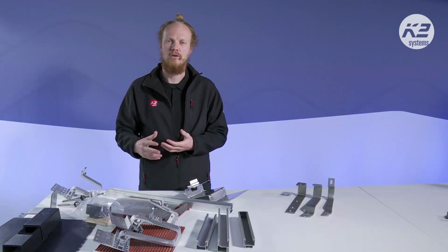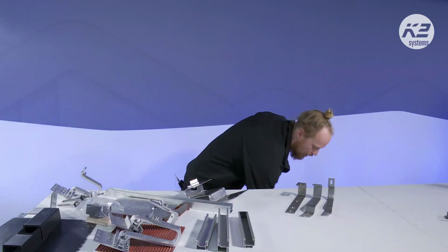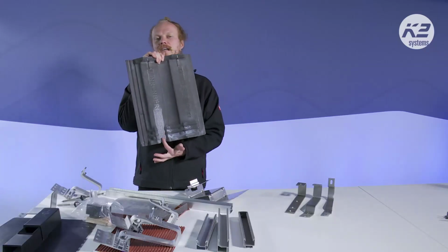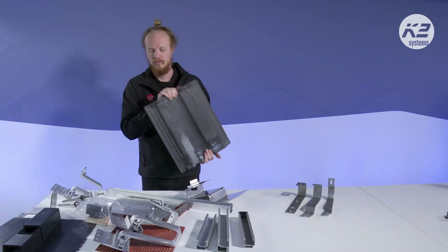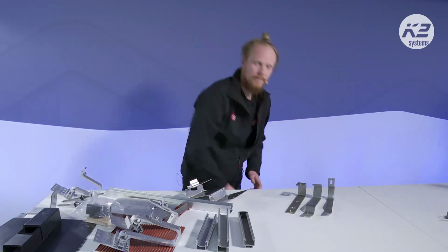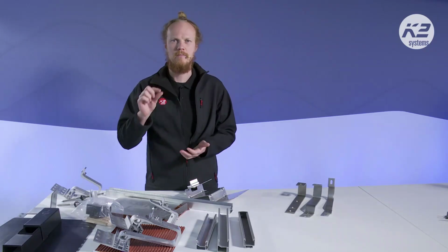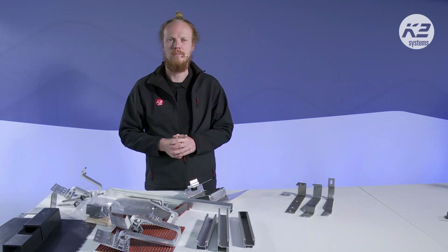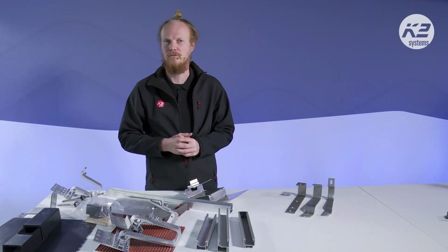Potentially the methodology where we grind the tile, and I just have a little sample here that we spoke about last week, where you can see part of the tile has been cut out. This is usually required for tile roofs generally speaking, but it doesn't really work on the flatter tiles because you create such a thin point where it will probably just crack. So we need to look for different methodologies to fix the mounting system to the roof.